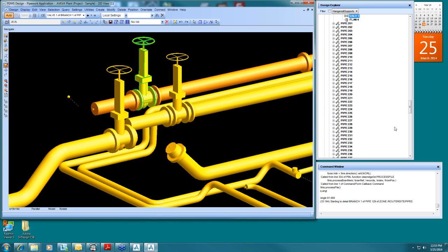We have done several jobs where we used laser scanning for offshore, and where we use the point cloud within PDMS to be able to identify tie-in points and for demolition and so on and so forth. But in that case, we have to back model all of that because we didn't have an interface or a mechanism to pull in a model like with ClearEdge 3D.